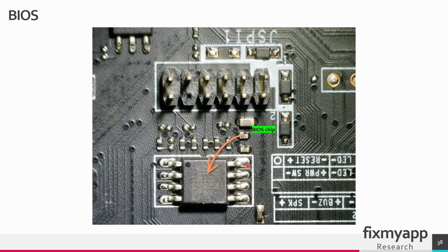When troubleshooting a motherboard, it's essential to work in steps to identify the source of the problem. I began by visually inspecting the motherboard for any signs of physical damage. This includes looking for burned components, swollen or leaking capacitors, or any visible damage to the PCB traces. Even a small crack or scorch mark could indicate a failure point.